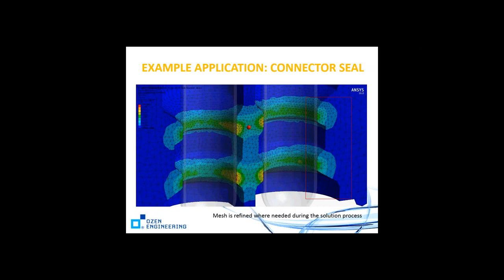It will say the element gets distorted so much, the original mesh gets distorted so much, that it can't solve this because of the Jacobian ratio, something ANSYS checks internally. When the element turns inside out, it says the Jacobian ratio has gone negative, and it will probably stop in version 14. If you have smaller elements in that area, hopefully it can keep track of the elements. Well, not necessarily. Even with smaller elements, they may push on each other so much that it may still turn negative. But this method is a lot better.